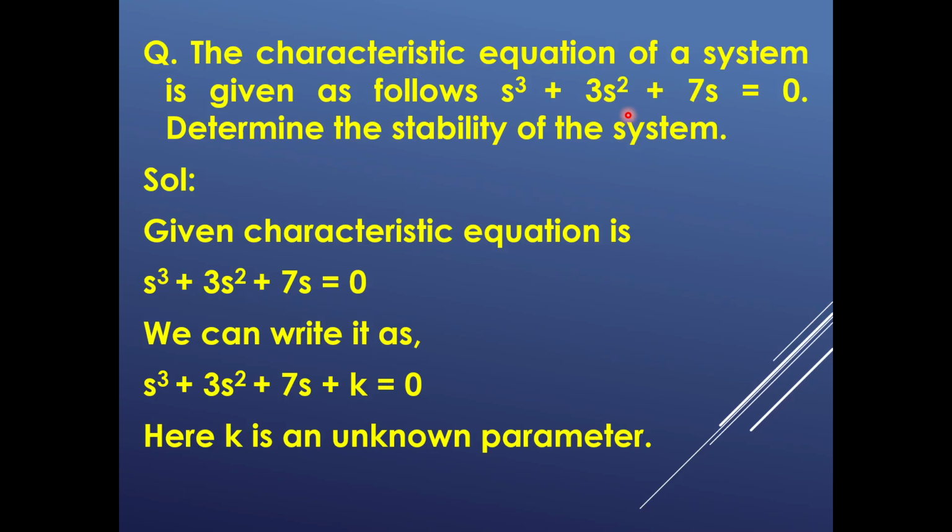So in this given question they didn't mention which method we have to use to determine the stability of the system. The method is not mentioned, but the characteristic equation has been given. So whenever the characteristic equation is given to determine the stability of the system, then it is better to go for the Routh Hurwitz criterion method.